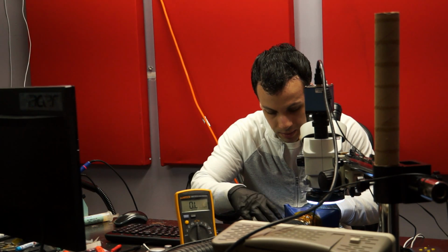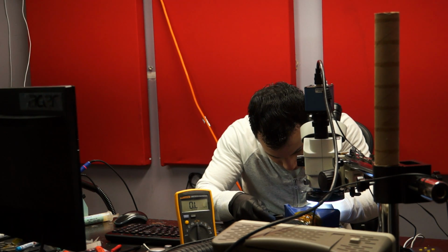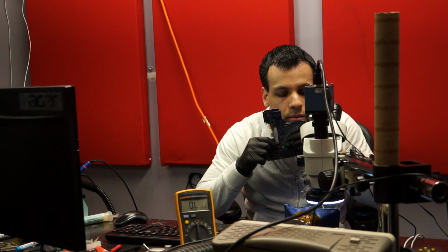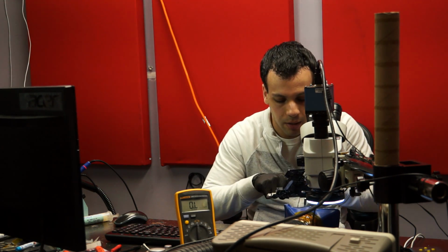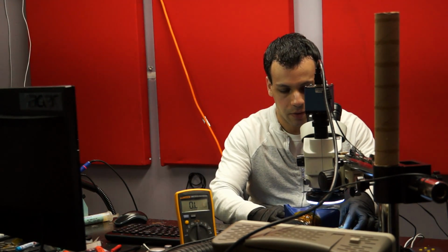Did PP3V3_S5 go? Oh. The fan's not spinning because of this friggin' connector. I'm probably just going to have to replace it. Alright, let's see. Well, I didn't turn it on because the CPU is not getting warm. So let's go back and see if PP3V3_S5 is present, shall we?